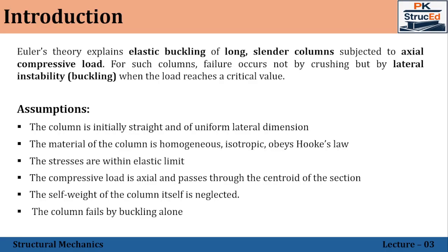Euler's theory explains the elastic buckling behavior. Here, the failure occurs not because the material reaches its crushing strength, but because the column becomes laterally unstable. This critical load at which the buckling occurs is called the Euler's critical load.